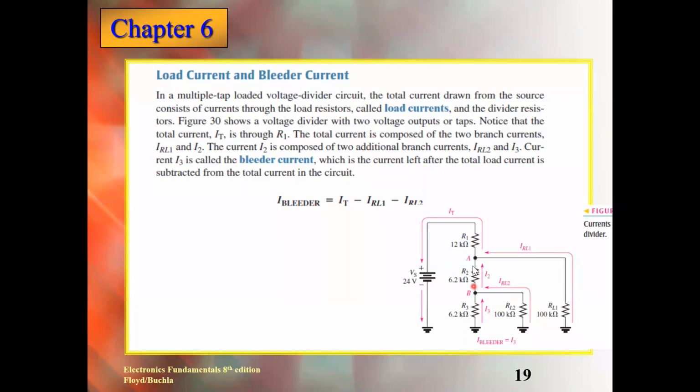Then calculate the current. R1 is still there. So R1 will be in series with this combination. So what you said, first, this is a combination because they are in parallel. So you will solve this one first, then after that you will calculate with that one. Okay, we'll approach it this way.